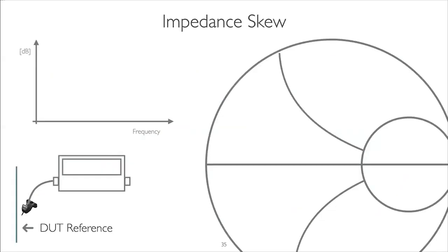So what affects impedance skew? Obviously, if you have a single carrier, a CW signal, you have a single dot on the Smith chart. That's represented by this multiplication sign here. So as you increase the bandwidth, the signal that you're presenting will have a certain impedance skew. Okay, that's one factor. As the bandwidth increases, the skew increases, directly proportional. Again, the wider we go, the greater the skew. This is basic math. We can calculate that. We know exactly what kind of skew we're presenting.